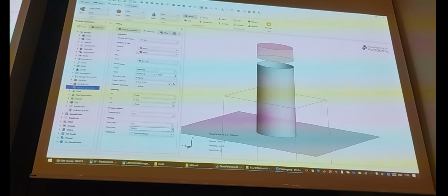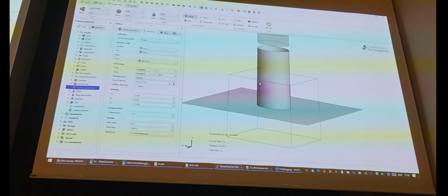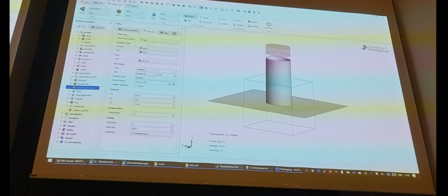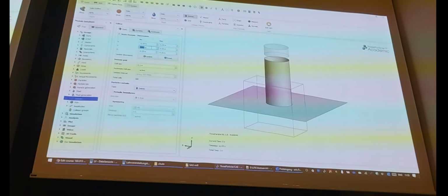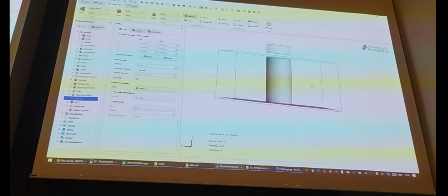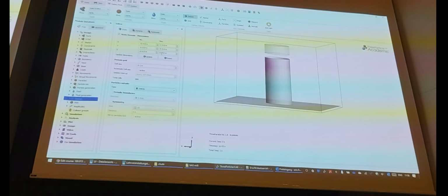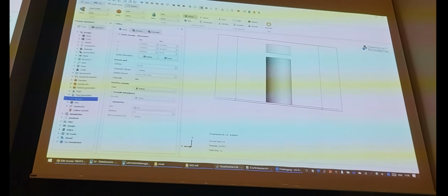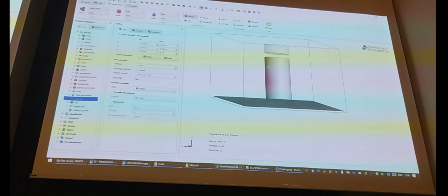One major thing, our domain. The domain, if you look at that, not working with that because our particles are generated here and would be deleted instantly. In the last simulation we didn't address it because we stick inside of our domain. Now we need to adjust that a little. So here you can change the size of your domain. And a good start point would be automatically update and try to fit everything around the particle, the boxes, except the one that is set to no collision. So you need to adjust that a little in its height, a little bit higher, something like that, and you're good, more or less. So doesn't look so bad, right? Everything is inside, looks good so far.